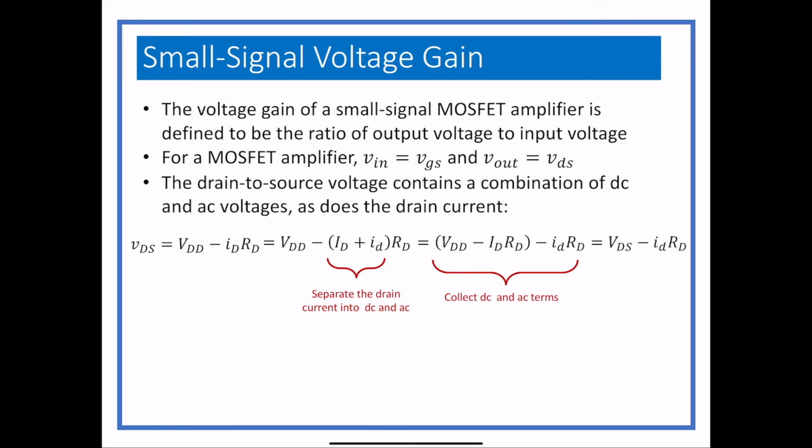And if you think about it, it's just saying that you have a DC value VDS, and then there's going to be a fluctuating value, because iD, being an AC value, is going to go up and down slightly. So the voltage right at the output is going to go up and down, and it actually goes up and down quite a bit, because it's the output.